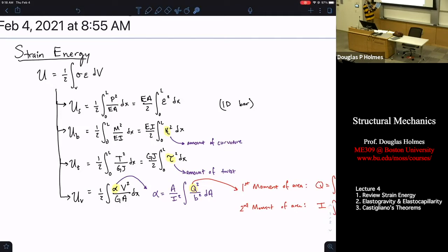Axial load, P, pairs with your elastic modulus, because your axial load acts to stretch an object. Shear load pairs with your shear modulus. Your bending moment pairs with EI, your elastic modulus times your second moment of area. Your torques, which cause twisting, tend to distort areas. If I twist this thing, I'm tending to distort the cross section of this shape. Even if I was to slice through there, you would see curves undulating along this whole object. So your torque is tending to distort the shape of your object.